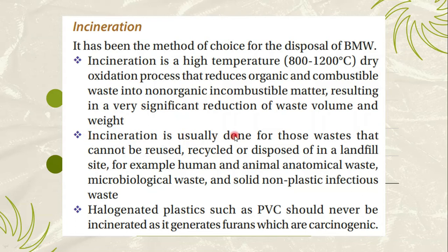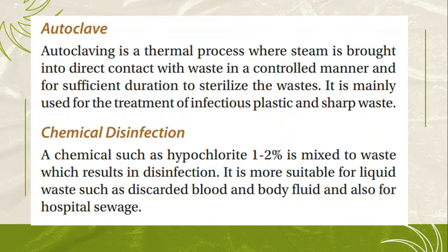Incineration is usually done for those waste that cannot be reused, recycled, or disposed in a landfill site. For example, human and anatomical waste, microbiological waste, and solid non-plastic infectious waste. Halogenated plastics such as PVC should never be incinerated as it generates furans which are carcinogenic.